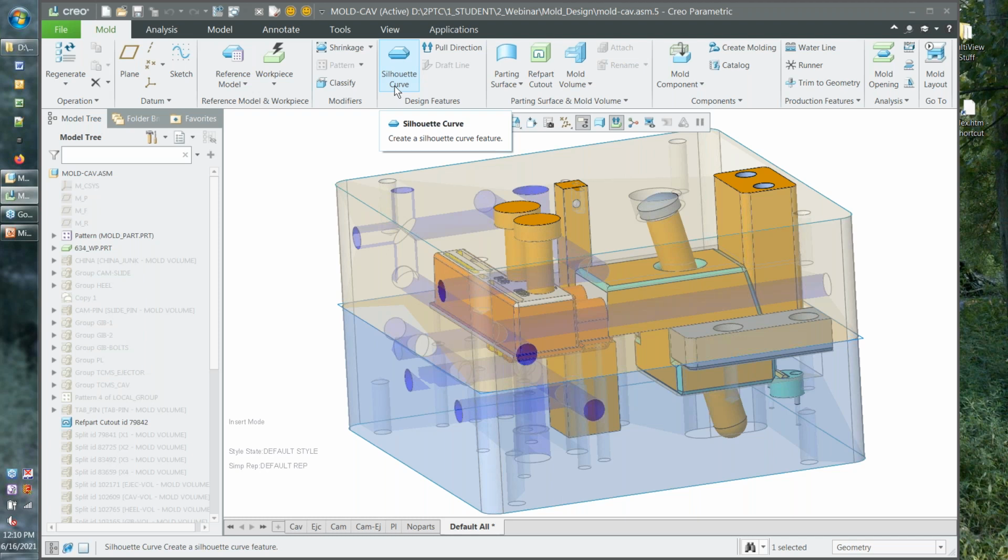If we're molding it into and holding it obviously on the core side of the tool, a lot of times boundaries that are very short, something 3 millimeters or less or 100 thousandths, sometimes those get left straight and they get pushed off anyway. That can cause problems with silhouette curve creation.